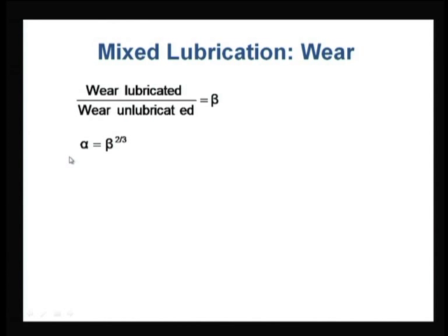So, basically wear is happening because of the friction junctions. If there is no friction junction at all, there will not be any wear. If there is adhesion, that is why the wear happens, adhesive wear. If scratching or plowing is happening, that is because of the friction mechanism, that is why abrasive wear comes into the picture. Similarly, fatigue will happen because of some sort of confinement and some coefficient of friction, causing some adhesion, losing some particles. So, everywhere wear is related to friction.